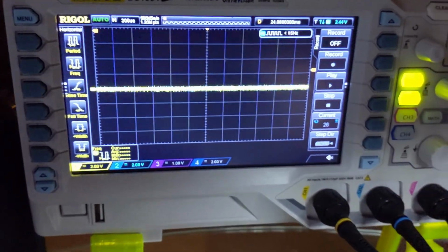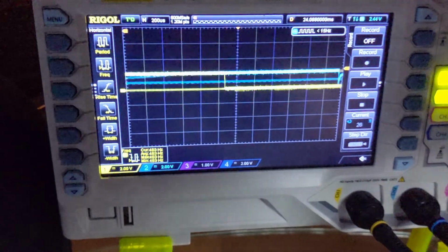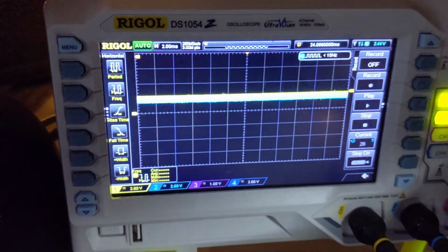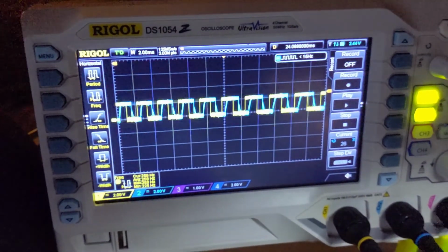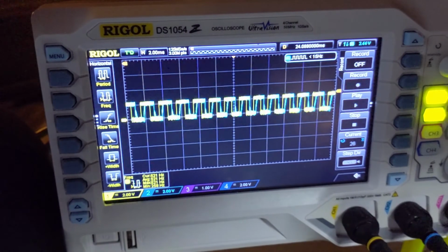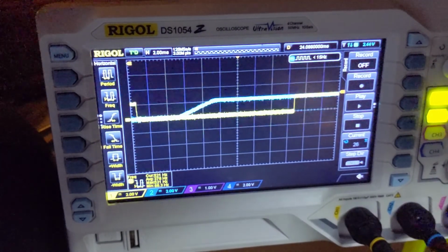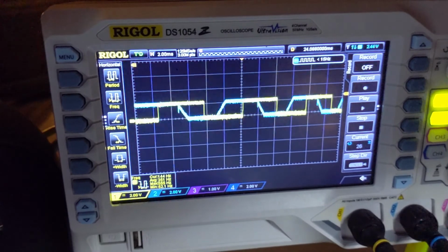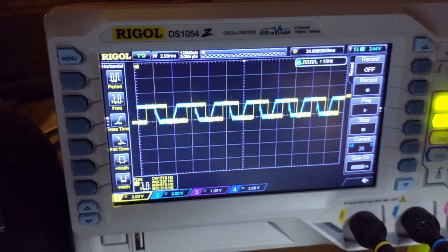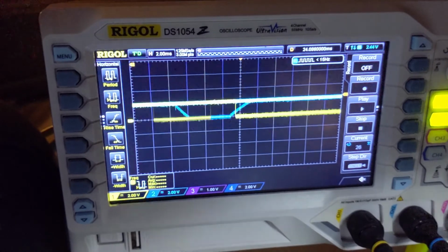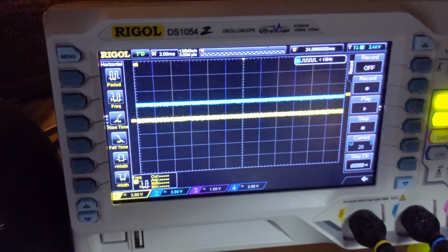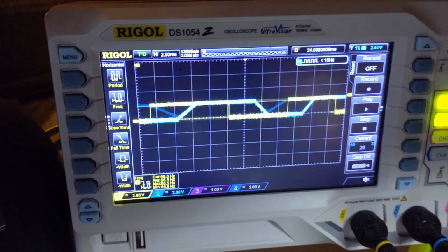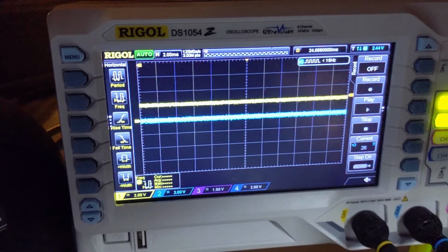Okay, so this is what the signal looks like. Let me zoom out a bit. This is 2 milliseconds. So you can see that's turning counterclockwise, and if I turn clockwise, it's kind of hard to see here, but the blue signal is rising first. And so from this signal, for each pulse generated, you can generate 16 points of position, non-interpolated.